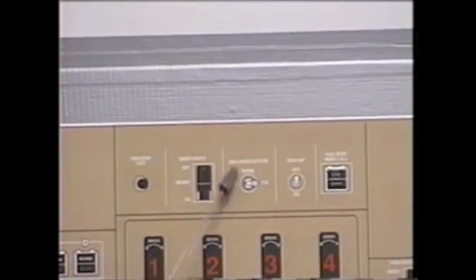Moving to the right with the emergency exit lights, 3-position switch: off, armed, and on. The emergency exit light batteries will charge with this switch in all 3 positions provided DC bus 4 is powered. If you reach up and place the emergency exit light switch to on, the emergency exit lights will come on. The batteries will be powering the lights, and if DC bus 4 is still powered, it will continue to charge the batteries. However, the discharge rate is greater and the battery charge will deplete.